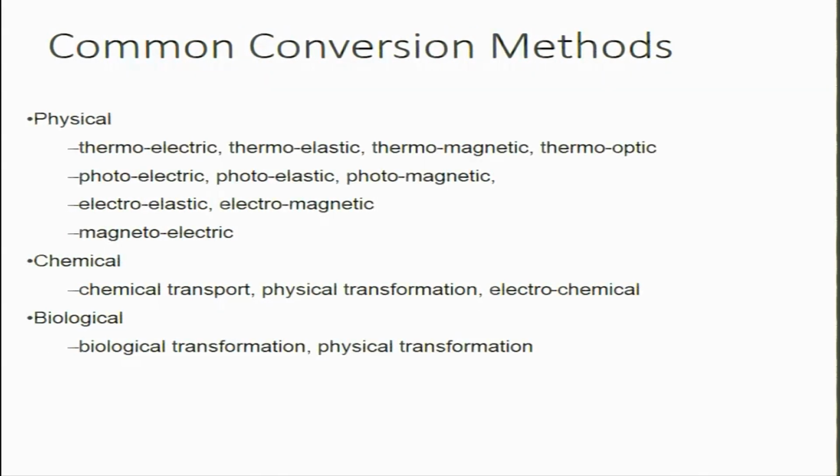So, the common conversion methods are classified based on what you are converting as the principal source of the measurement. If the measurement is physical in nature, it would cover a lot of domains like thermoelectric, thermoelastic, thermomagnetic, thermo-optic, photoelectric, photoelastic, photomagnetic, electroelastic, magnetoelectric, electromagnetic, and so on and so forth. These are all where the measurements are physical in nature, and you are converting them into signals which are either magnetic or light based, or